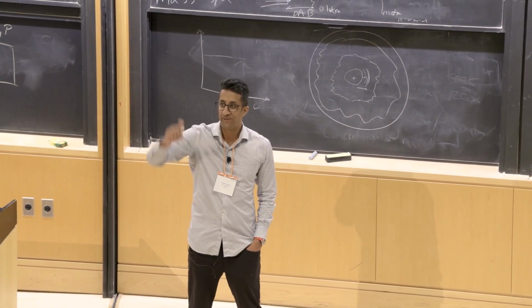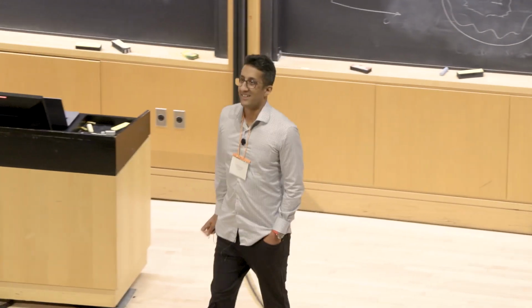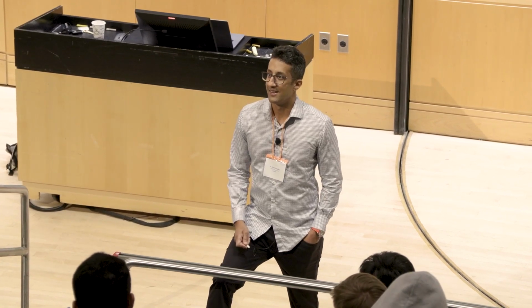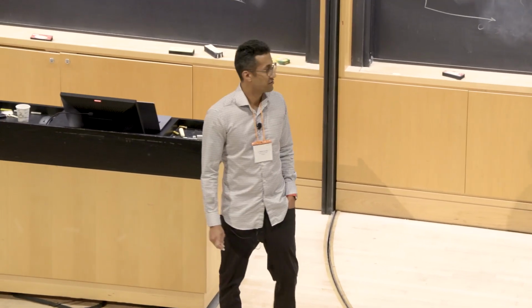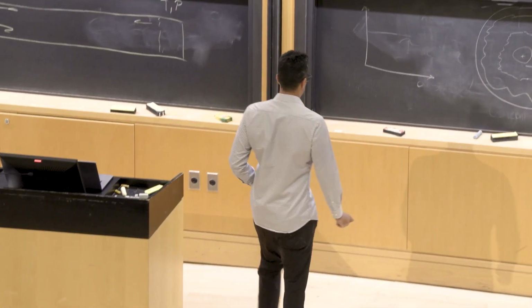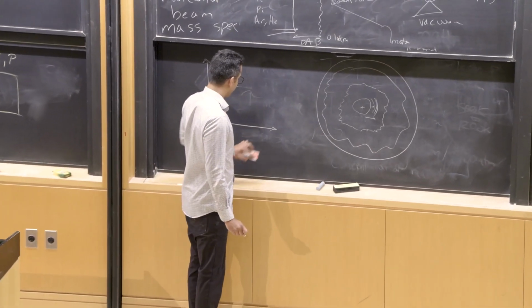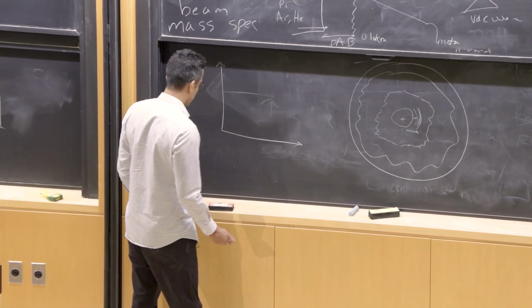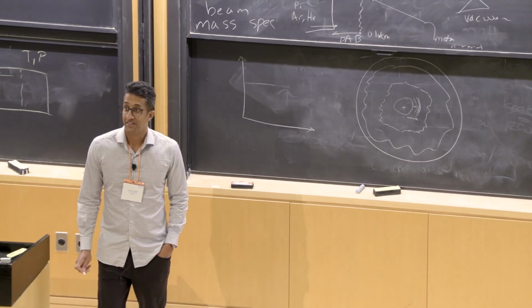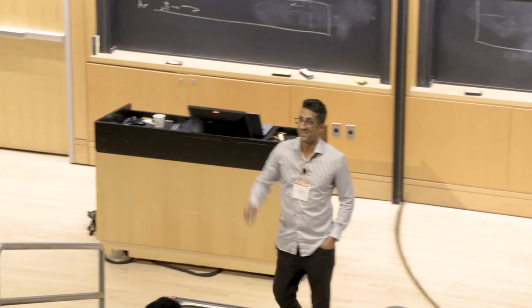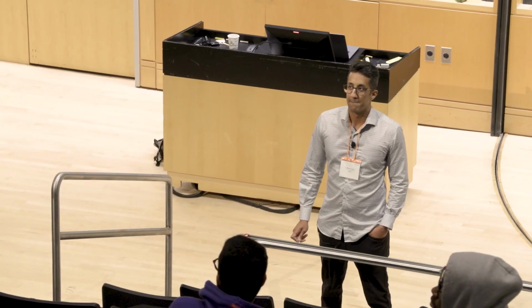You are? In what device? Constant volume? Okay, he's doing a constant volume chamber. Where's that at? West Virginia? Okay, and you use Schlieren imaging, which is looking at the density gradient to measure the flame. So you'll be measuring the flame. Do you look at the stretch effect? Yes. Okay, can you tell us about it? So the stretch is defined by the curvature and strain.